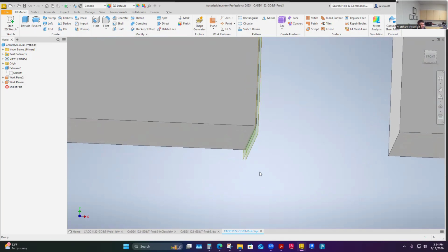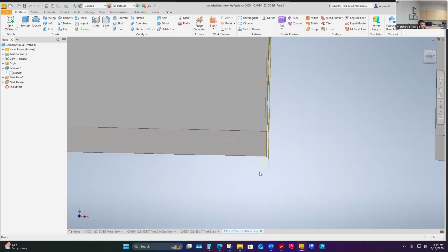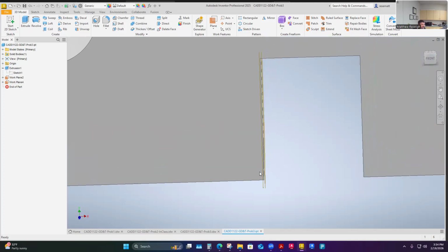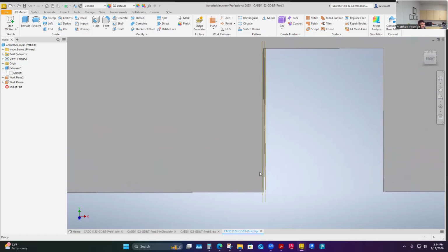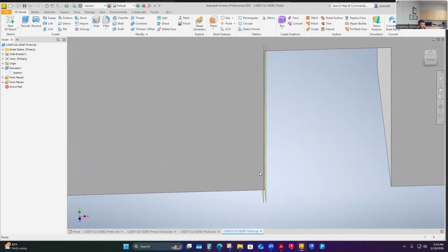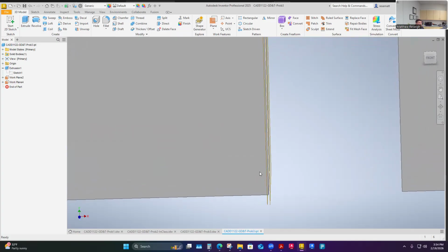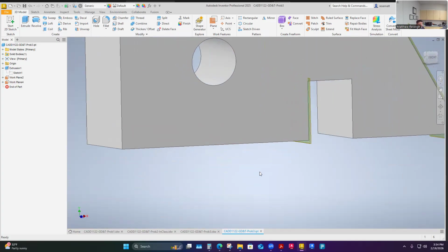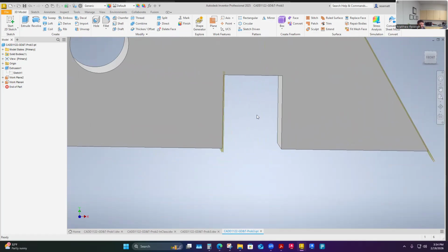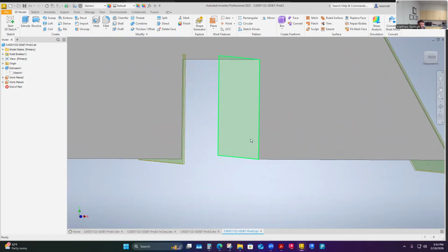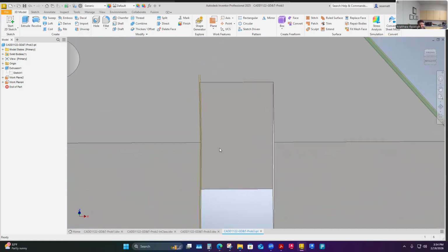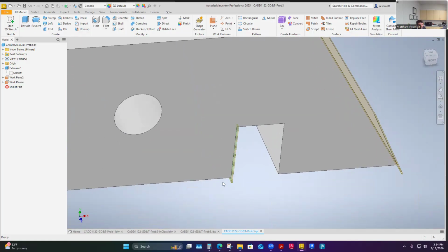I'm doing that same kind of parallel plane control on that theoretically exact size, and saying that actually that can live within this plane here, these two parallel planes. And the same geometric control applies to this surface as well. That's how we're controlling it, is between two planes. Okay, as long as that surface lies between those, it's acceptable.